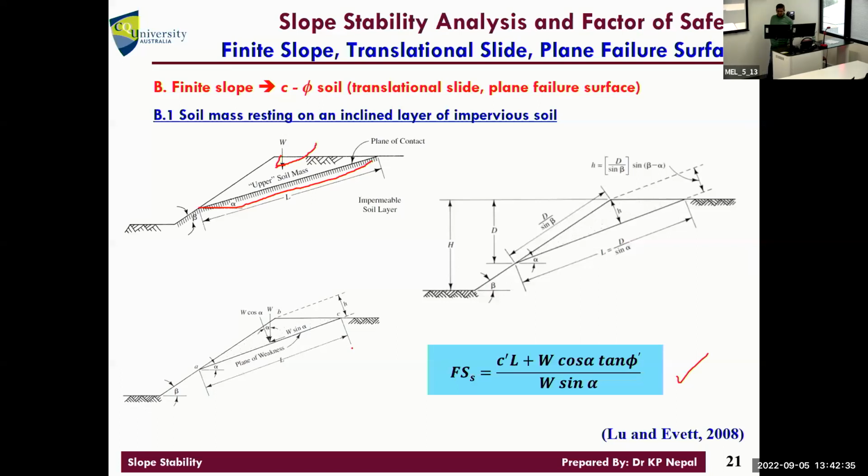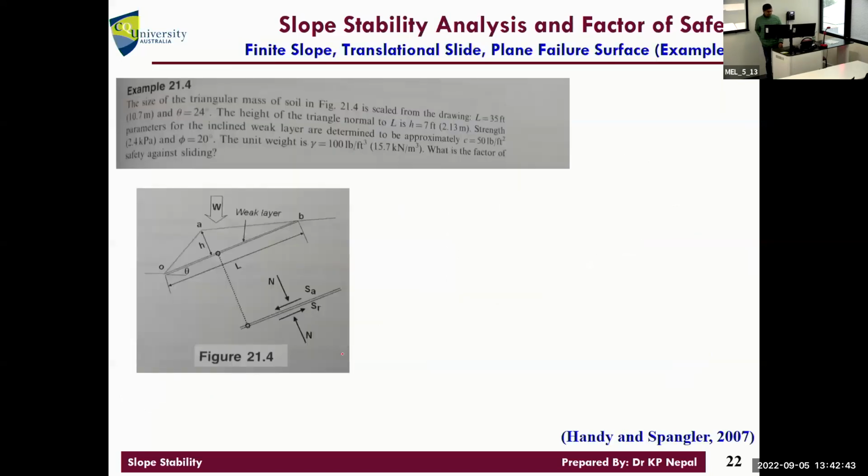W is weight of the swell, that triangular block. You copy it? All right, let's go. Can you calculate weight of that now? Let's do it slowly. What is the area of triangle? Half base times height.